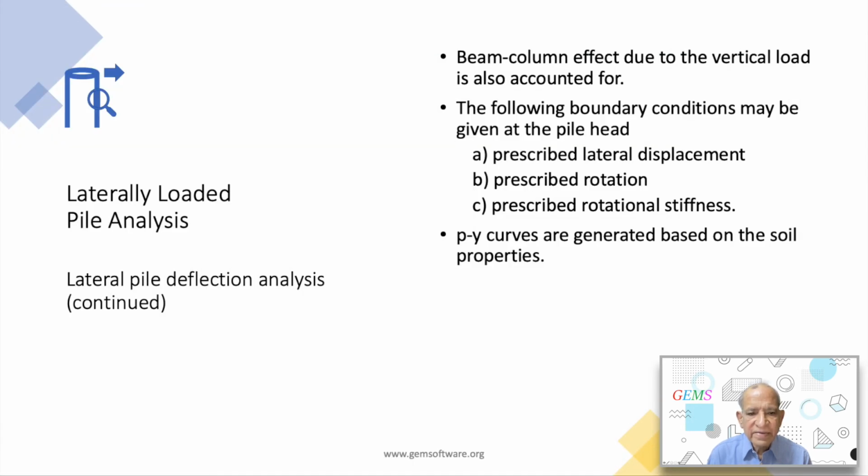Pile head conditions. The following pile head conditions are available: no condition or free head, prescribed rotation, and prescribed rotational stiffness. Lateral load and moment could be applied at the pile head in addition to a vertical load. The FE model incorporates the beam column effect.